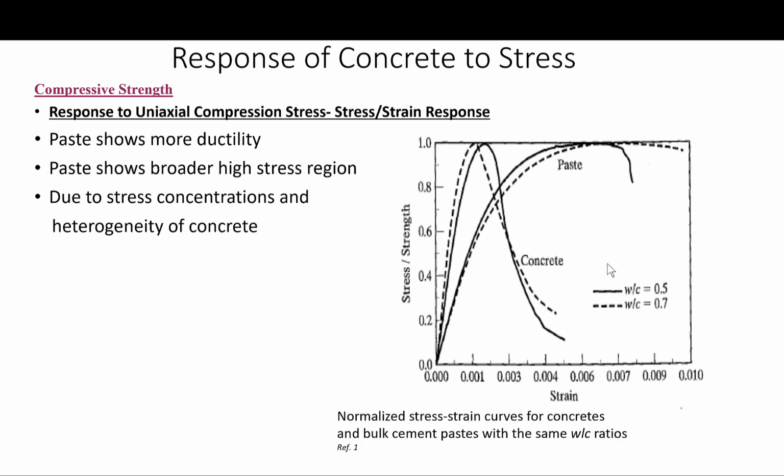Okay, so let's reiterate again what we have said before. The response of the cement paste and concrete, or mortar, is quite different, as shown here in this curve. This is the curve for concrete at 2 different water cement ratios, and this is for the paste, the same. This figure compares the stress strain curves for cement paste and for concrete, with water cement ratios of 0.5 and 0.7 for both cases.